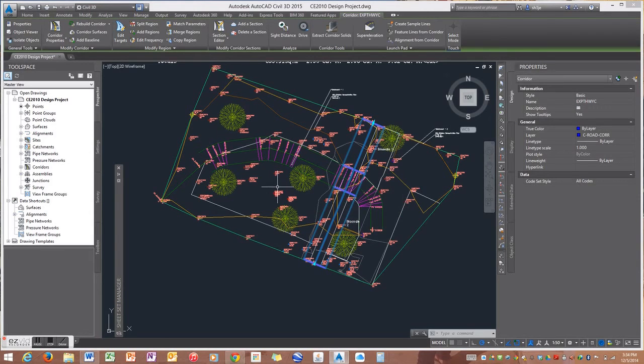I decided to utilize this existing natural catchment area, and instead of doing extensive regrading, which would have been expensive and time consuming, implemented 2 bioswale sections to catch that water and help it to naturally filter down into the groundwater, instead of adding to the existing stormwater load.